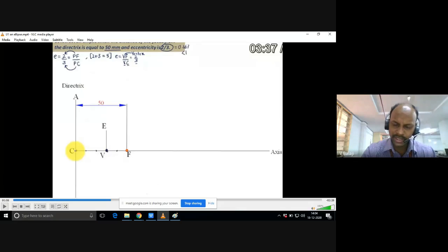Better to always use the mini drafter, because you already have the axis line, the horizontal line. Match your mini drafter scale to the axis. Automatically, the other scale gives you 90 degrees, so you need not use any protractor. If you use an ordinary scale, it's very difficult to draw a perpendicular line. So always use the mini drafter. It's multi-purpose. Earlier, while dividing the line into n equal parts, we drew parallel lines with the mini drafter. For drawing vertical lines also, use the mini drafter.